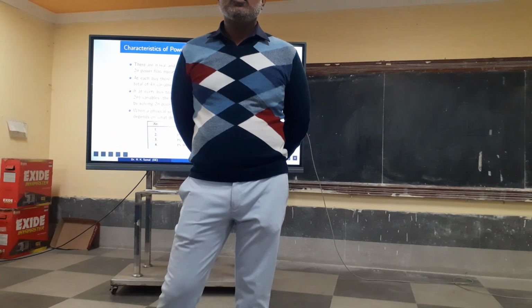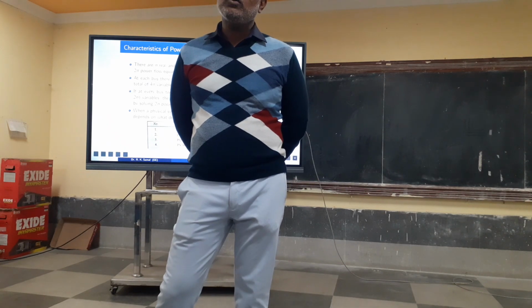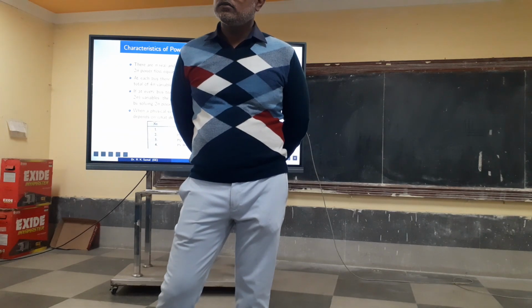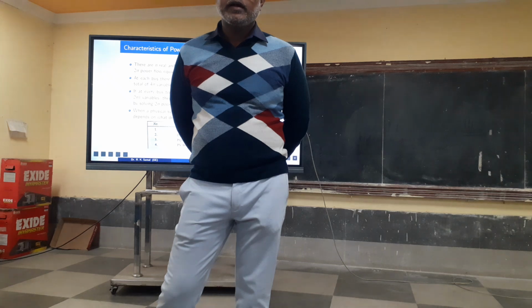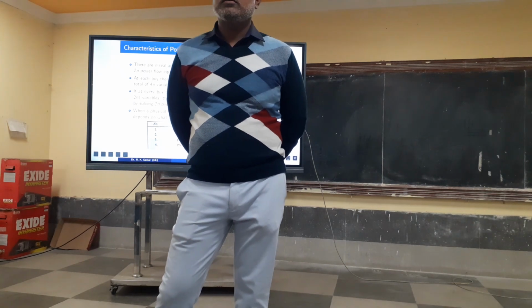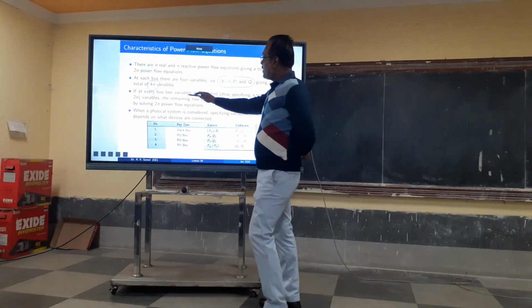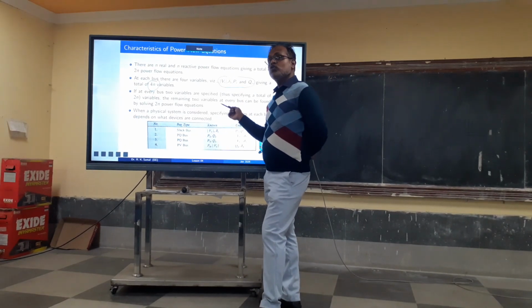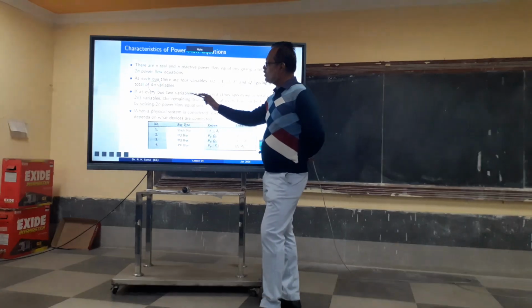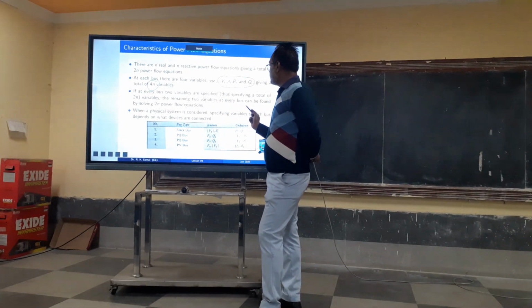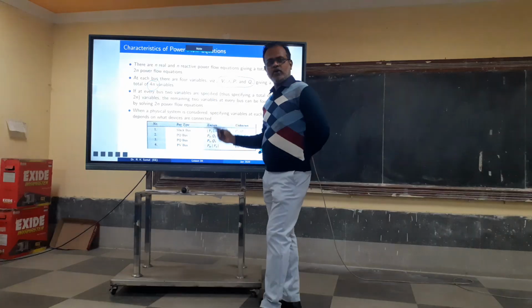So either you can assume V magnitude or angle, or both. We'll see that. So if at every bus two variables are specified, that means a total of 2n variables are specified, and the remaining 2n variables can be found by solving the 2n power flow equations.